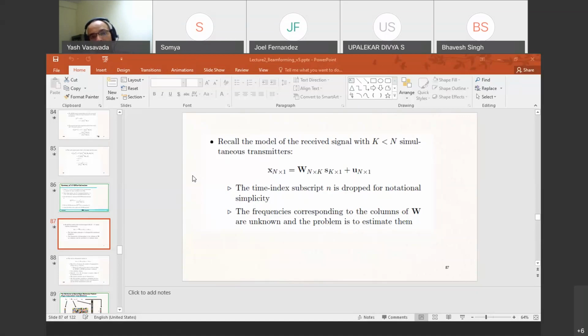and then do eigenvalue decomposition on that, what I'm going to see is a bunch of eigenvalues which are going to be smaller. And if the signal to noise ratio is high, then significantly smaller compared to the other eigenvalues. And it is these small eigenvalues which tell me a lot about where the incoming signals are in the frequency domain.